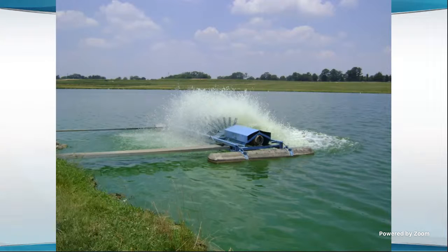This aerator here, we originally got some real high numbers for oxygen transfer, around 4 to 4.5 pounds of oxygen per horsepower hour. And we later found out that the tank we initially did those tests in, I didn't get into this by my own intention, people wanted it done, and we used what we had available to us. And that tank wasn't quite big enough, and it resulted in us reporting a higher value than they really transfer.